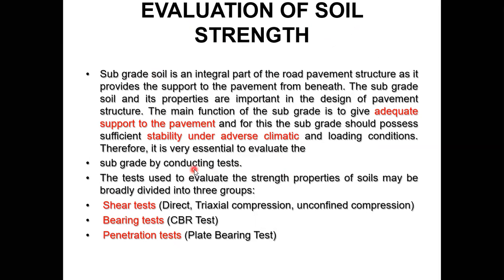There are different tests you conduct to find the strength of the soil: shear test, bearing test, penetration test. In shear tests, there are direct shear test, triaxial compression, unconfined compression. There are a number of shear tests. For bearing tests, there is the CBR test, and penetration test and plate bearing test are there. As I already told before, we are going for only one test, that is the CBR test.